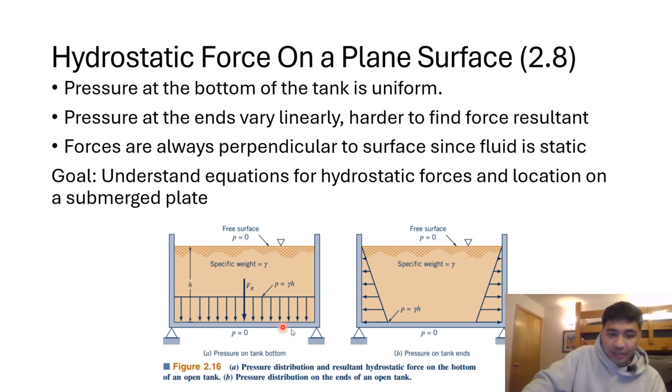And this is the pressure on the tank at the bottom. You can see it's uniform here, which kind of makes sense. This only works for static fluid problems though, right? No shear stress. Here in the diagram to the right, you can see the pressures on the side of the tank are not uniform. It increases as you get lower in depth, which is exactly the whole idea of this lecture, right? So let's go to our bullet points now that we explained the diagram.